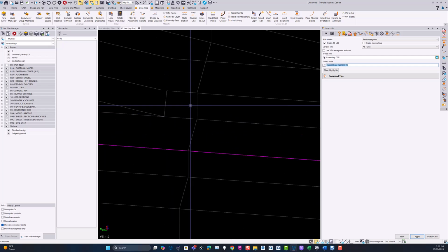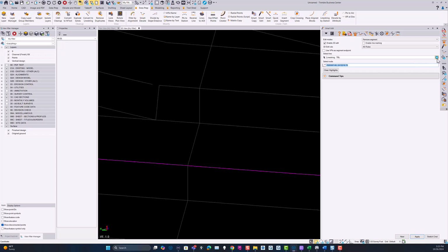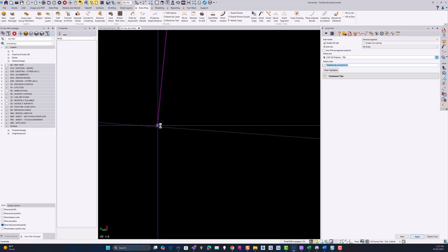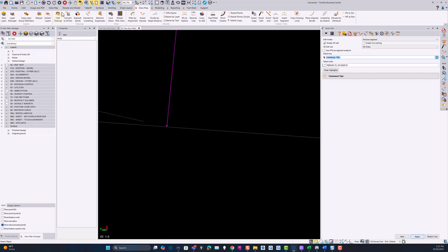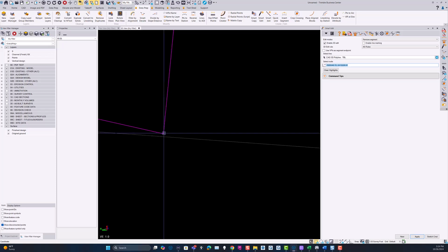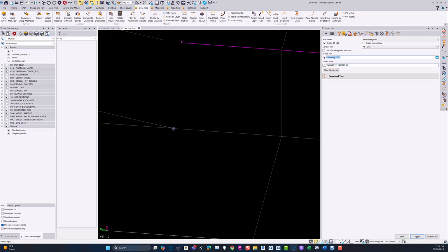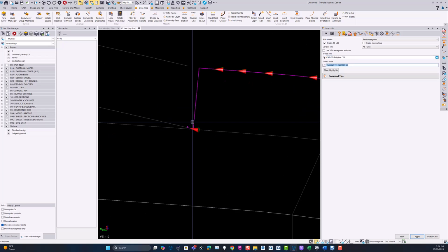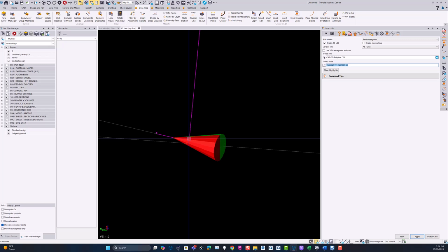So it's a two-click function, and it toggles between the lines. So here you get to pick the line and pick the segment, so you don't have to know which end of the line or whatever you're trying to remove. If you find that you click in the wrong place, again just go back into the starting point, click on here, and then you want to make sure you click on the line close to the end of the previous segment that you want to get rid of. So again, go to this one, and again zoom in on this and click on the segment end here.